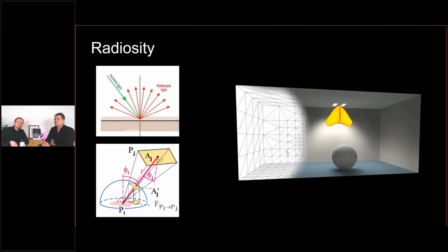It depends on dimensions, it also depends on what is in the room, and of course also the reflection of the walls. If you do not know the color of the walls or the reflection degree of the wall, then it's really hard to calculate correctly, because this has a big impact depending on the room, depending on how direct or how indirect the light is.